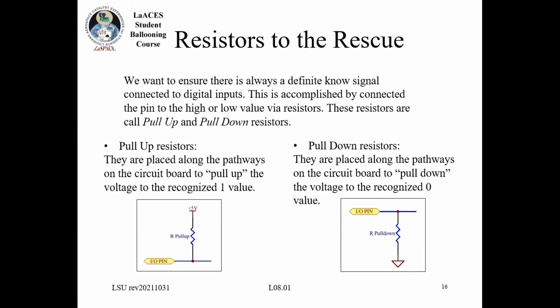And what that means is when I don't have an input signal here on the IO pin, or actually, this would be the pin on this side, and the signal that you actually care about is here, I know the pin is in a known state when I don't have an actual signal here.